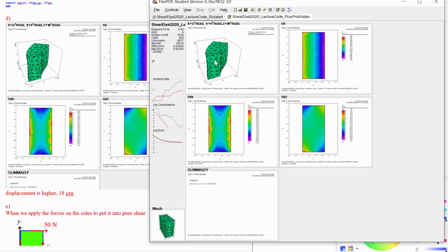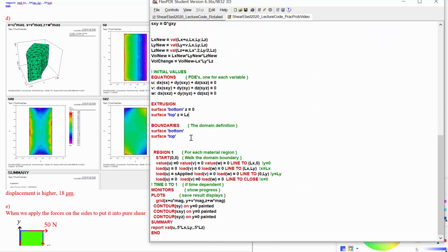So maybe that does explain why it would actually want to be buckling in the other direction, and that's what we're preventing here. Let's see if we can explore this a little bit. So we might be able to say instead that it holds still not on this side by setting the Z displacement equal to 0 everywhere on that side, but instead leaving that alone, right?